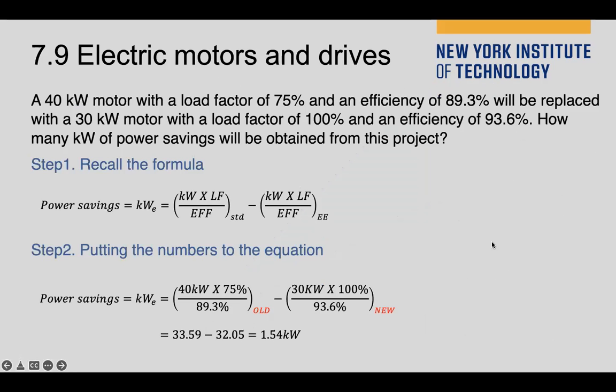Okay, the last question is about the load factor and the efficiency of the motor. A 40 kilowatt motor with a load factor of 75% and an efficiency of 89.3% will be replaced with a 30 kilowatt motor with a load factor of 100% and an efficiency of 93.6%. How many kilowatts of power saving will be obtained from this project? So such kind of